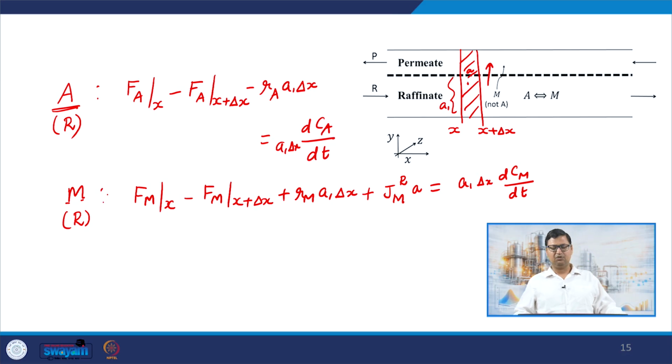Therefore, we also have to account for the actual mass transfer, the flux considerations, which will deviate the system from the equilibrium situation, right? So in reality, we should always go for what are known as rate-based models or non-equilibrium models, because non-equilibrium is closer to reality than the equilibrium that we assume.